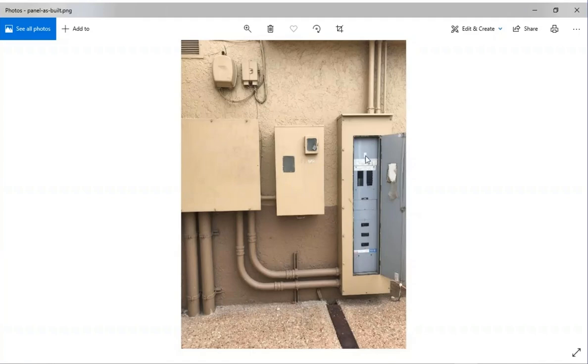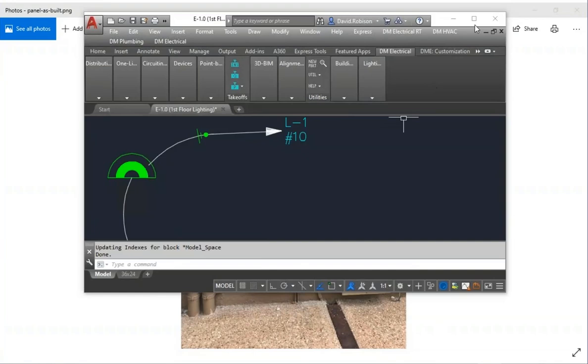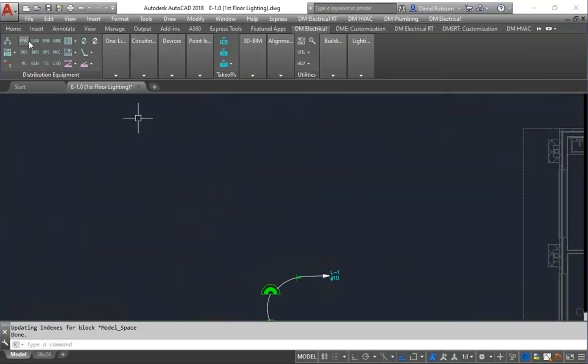And the answer is, we don't have any sort of distribution equipment that looks exactly like this. So when you have something like this, you kind of have to build it up with pieces based upon what matches in our software what you've got. So my recommendation was you probably want a 4-circuit switchboard, actually probably a 3-circuit switchboard with some bottom lugs. So you have these 3 breakers, and then a regular panel that you would do a feed-through connection to that switchboard on, and that kind of gets everything put together properly. So looking at that in AutoCAD, it would look something like this.